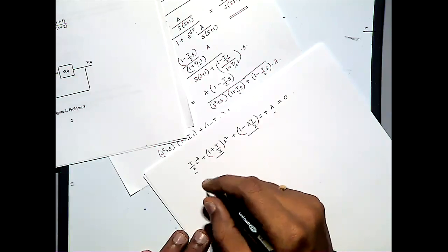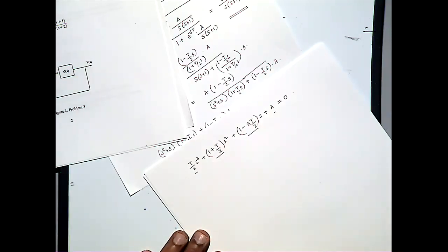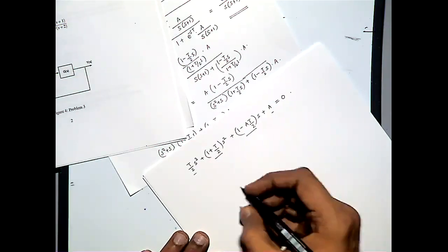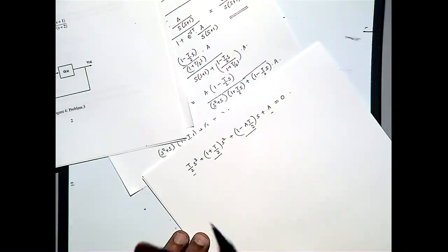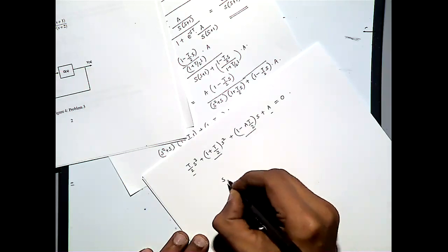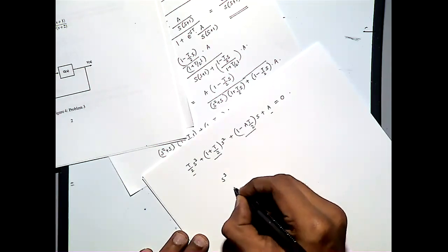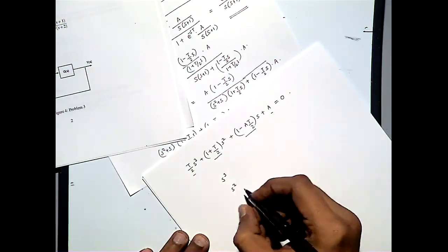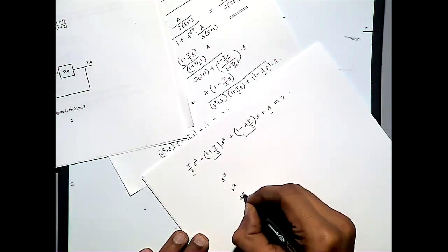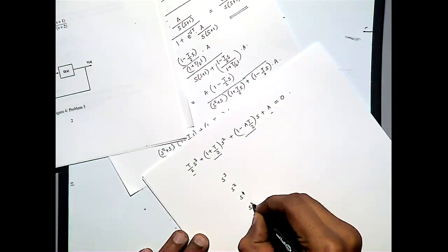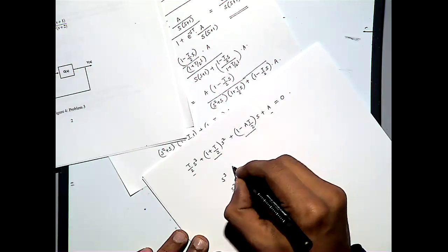All you need to find out is the Routh table and look at the coefficients in that one. If all the coefficients in the first column are positive, then you can say that for those parameters the system will be stable. So let's write down the table. Since the equation is a third order one, we will have 4 rows,